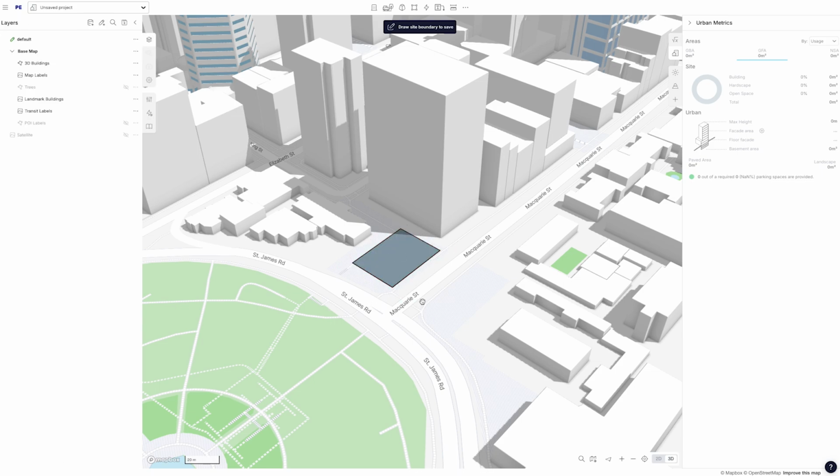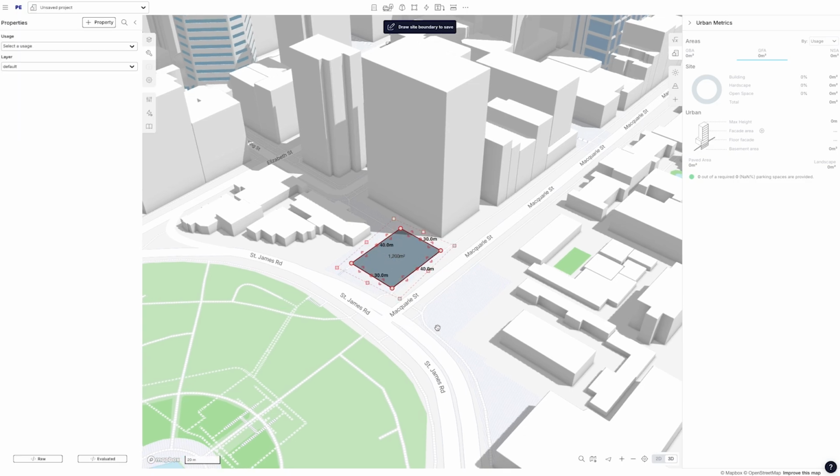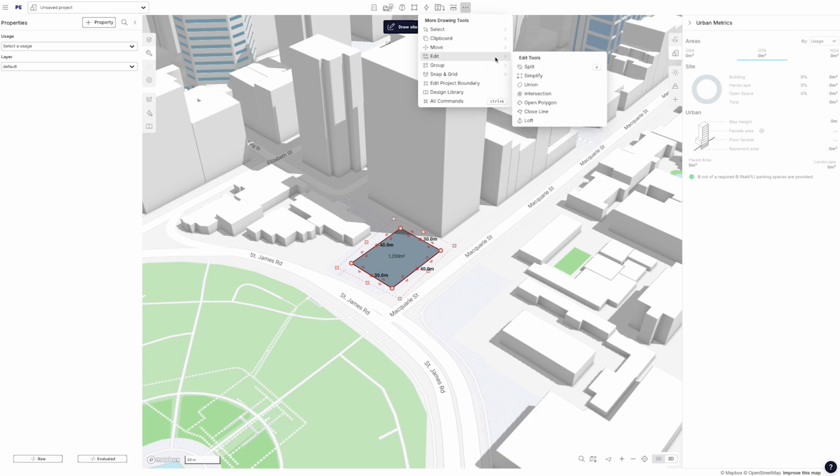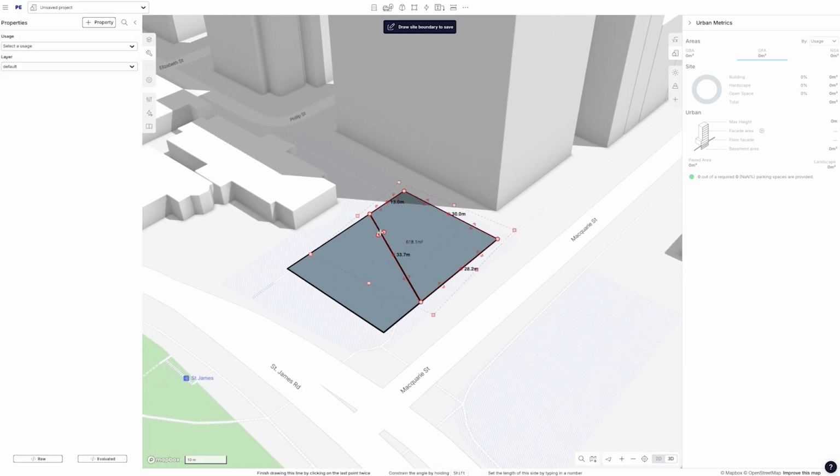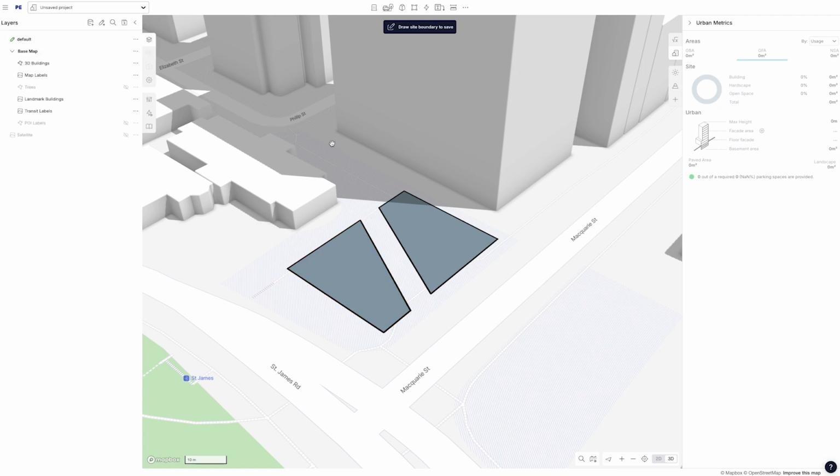And you'll see we get a gray rectangle, which I can select and deselect, just left clicking. And you can see it's got its areas. Now we can slice this rectangle. There you go. Got all these options here. So I'm going to click the split tool and I'm just going to draw like a diagrammatic split, something like that. And then I'm going to grab these handles, these extrude handles, and I'm going to extrude 3 meters that way and 3 meters that way. So I have a nice 6 meter floor plan.